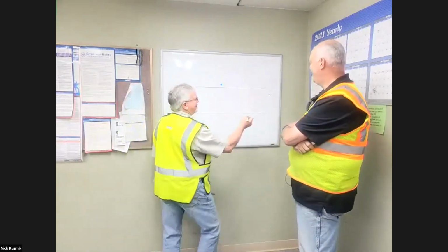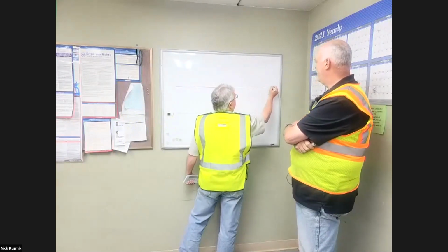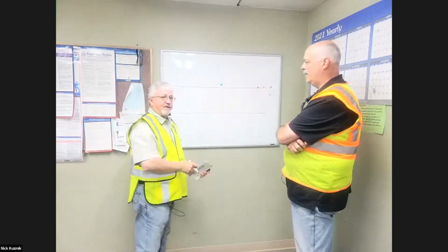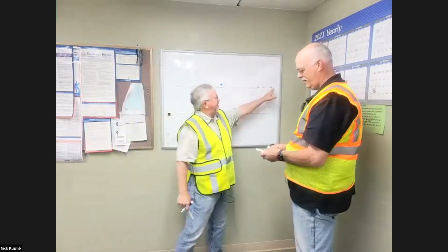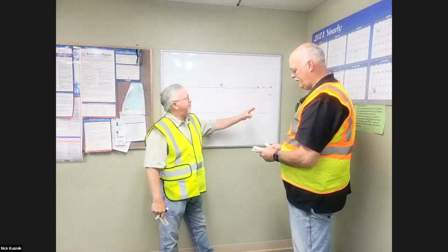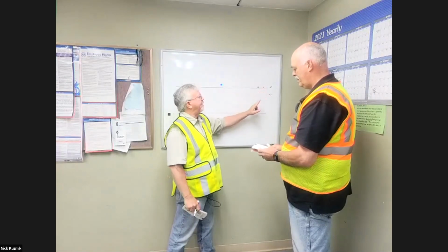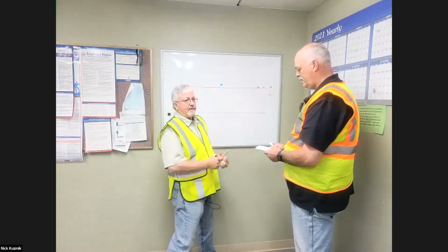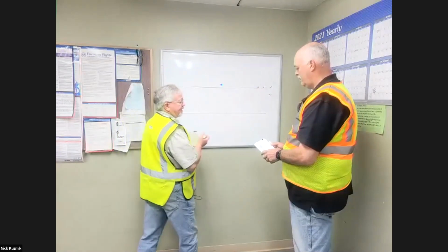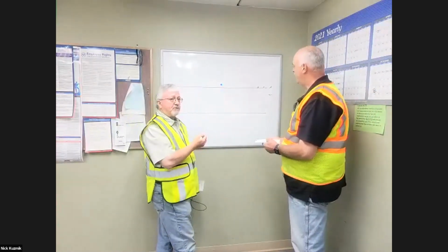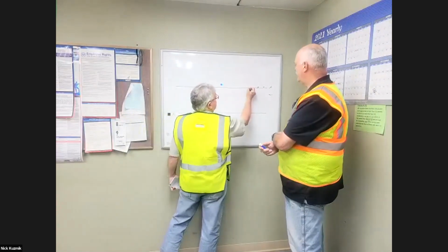So first you need to set up your signs. These will be the 3 signs. One will be letting the driver know that there's going to be a work zone coming up. The next one's going to tell the driver what's happening: you're going to channel into another lane. Then you'll have your flagger sign here. Further down, again, these spacings are identified within the work zone, based on the overall speed of the traffic. And then we'll have our flagger zone here.